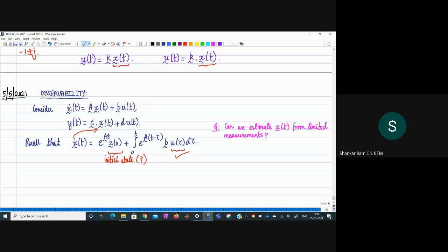If we recall its state space representation, we had four state variables: the vertical displacement of the sprung and unsprung mass, those are two state variables, and the speed of the sprung mass and unsprung mass. Now, if we were to implement a controller for the quarter car model to control the ride response of a vehicle, we would require measurements of all these four state variables. But that cannot be feasible in practice, isn't it?